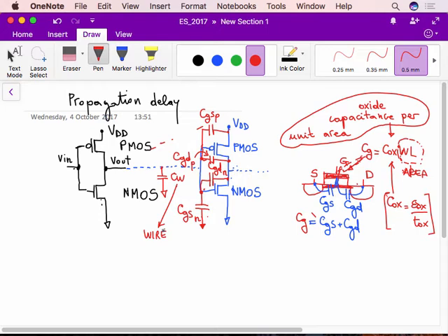So you can observe here, if you look at this in some detail, that all these capacitances have a common node, which is this one. This is the same node, and is connected to the output node. And then they have another node, which is sometimes the ground, or, for example, in this case, the output of the second inverter.